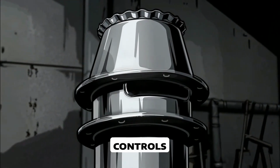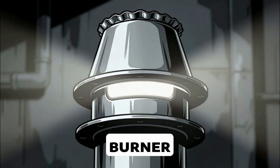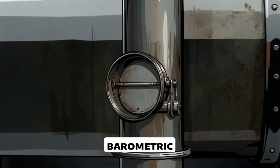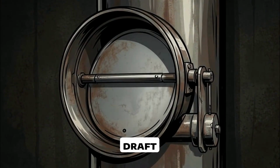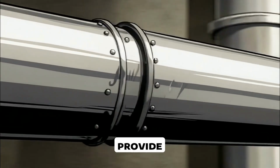Now, draft controls. A draft hood helps stabilize draft and protects the burner from excessive chimney pull or downdraft effects. A barometric damper regulates excessive draft but cannot increase draft beyond what the vent system can naturally provide.